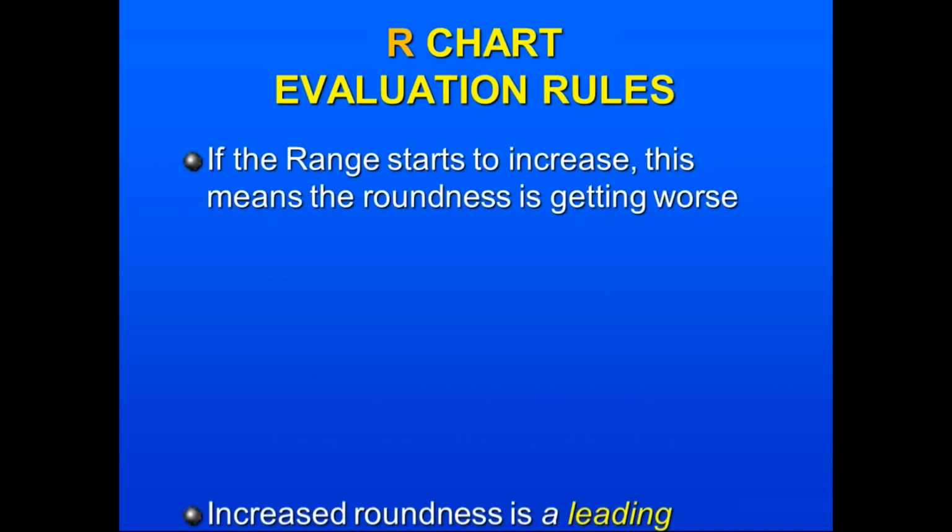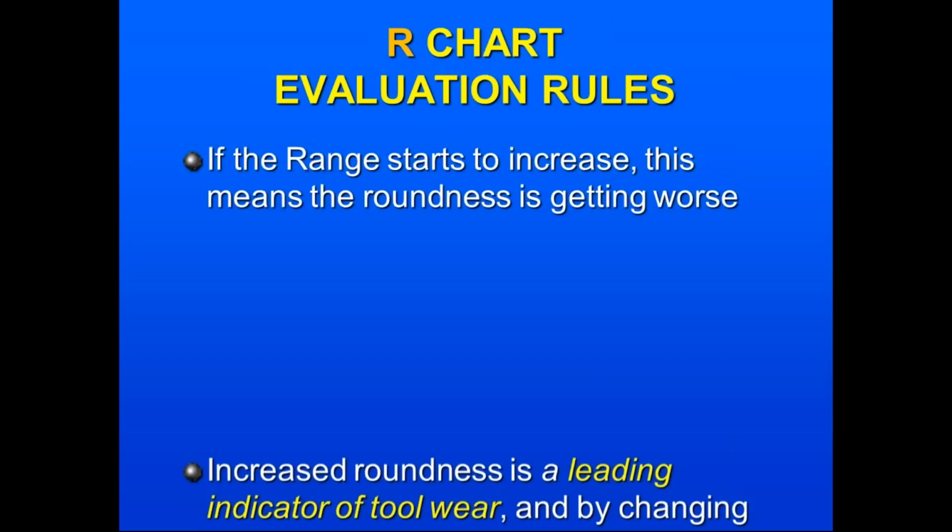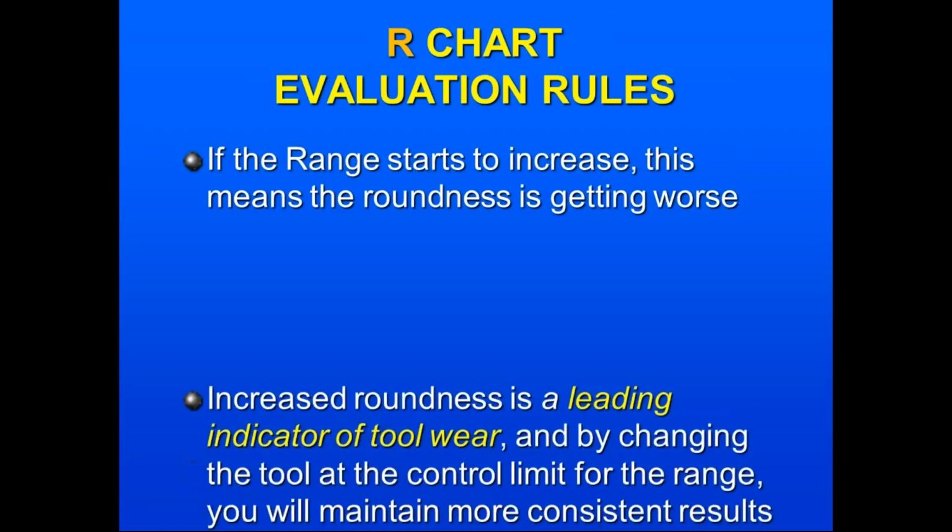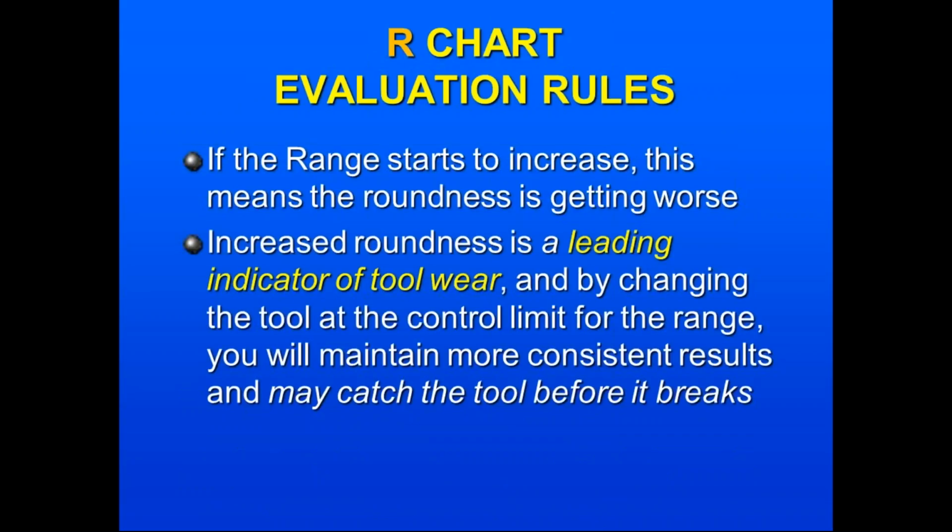You'll see a little more of a hook type of curve. Once we know the cause and you understand the cause, then you continue. If not, you need a fresh tool. From using tools in the past, you can actually set that limit at that roundness, pull that tool out, no matter how many parts you've made, and catch it before it blows.